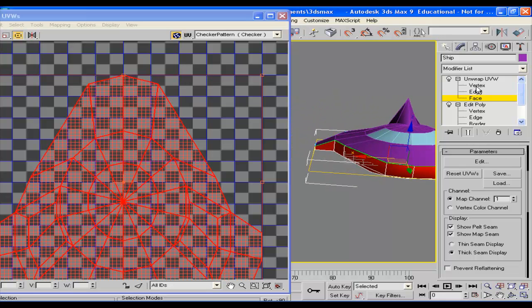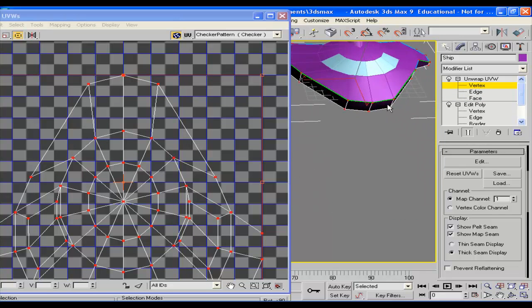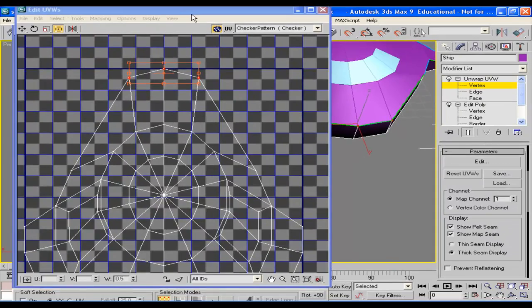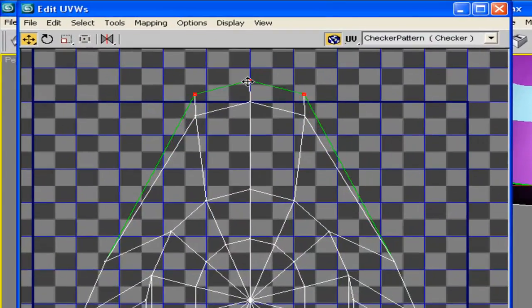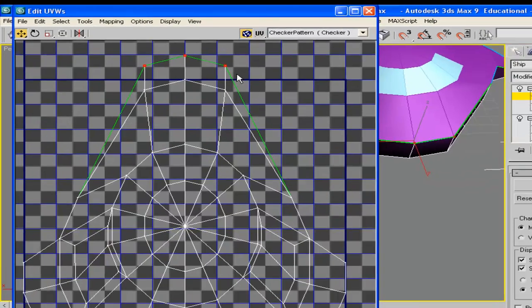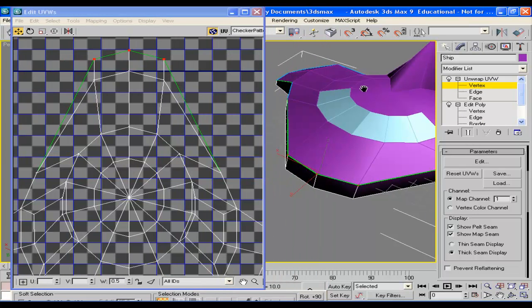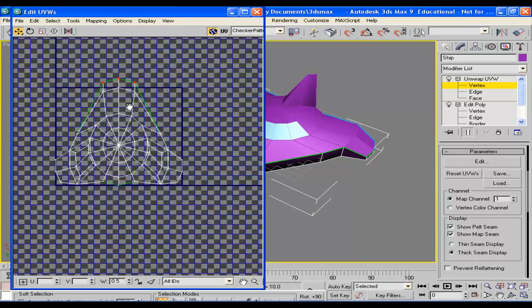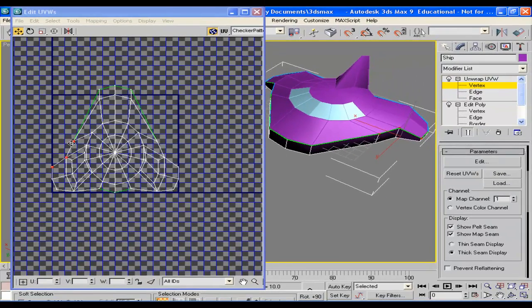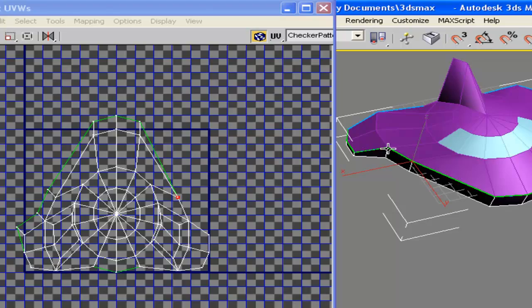What can we do? One thing we can do is go to the vertices, and let's select the first three. And look, they are selected now. And I'm going to use the move key to move them out, so that I can actually paint on this part. Otherwise, it's hidden, right? So now I'm painting. Press Shift, so that it's aligned to the vertical axis. And I'm going to go back, scale this a little bit, and select these three sides. Pull them slightly outwards, and also mirror on this side.